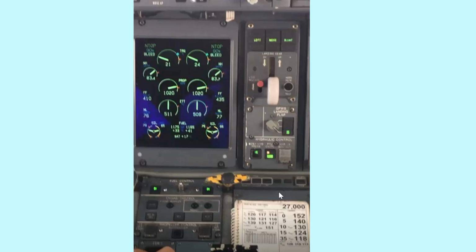In this particular configuration for this particular flight, for us to keep our indicated airspeed between those figures, somewhere around there, we must maintain a torque of 27%. That's a rule. But now, why do we do that? That's the question. Why is it that we have to match the torque value to the first two digits of the landing weight? That is what I'm trying to get to.